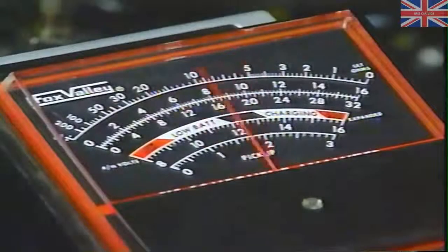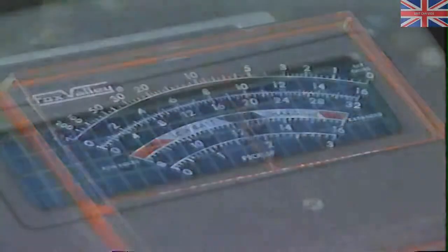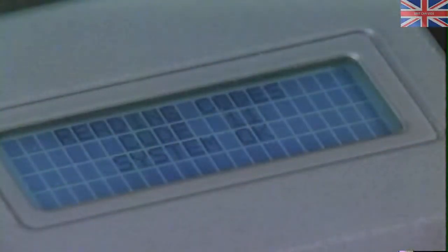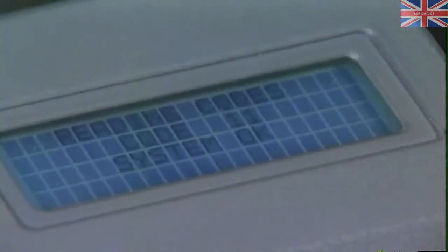The computer will now check for continuous memory codes. It will search its memory bank for any codes that have been held in memory. These codes would be the result of a prior fault in the system, not necessarily present at this time. A code 18. You should always repair the on-demand codes first and receive a pass code 11 before doing any other testing or any other repair work on the vehicle, even if a continuous memory code exists.